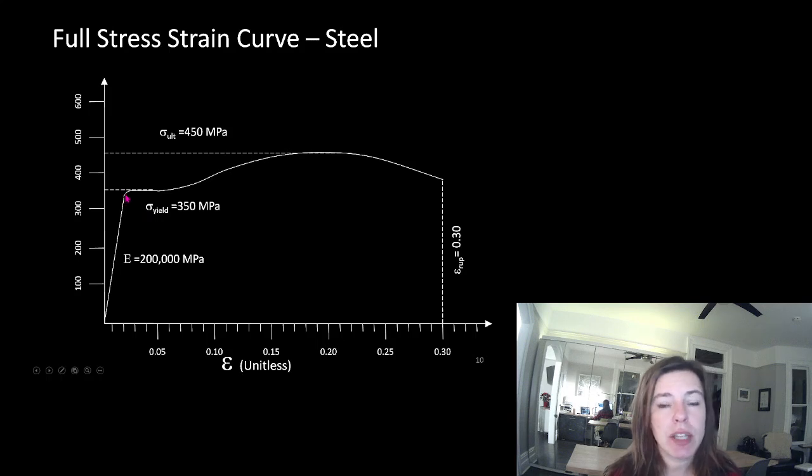Because what we want to do is we just want to know when it gets into full plastic deformation. So sometimes we'll say just when the extreme fibers start to yield, and then some members will allow it to yield all the way down to the neutral axis. But we don't want to go past that, because if we go past that, we're into very large deformations. We don't want to see very large deformations. If we see very large scale deformations in steel, which is different than exceeding our deflection limits, it's because we've exceeded our strength criteria, which I know can be confusing.